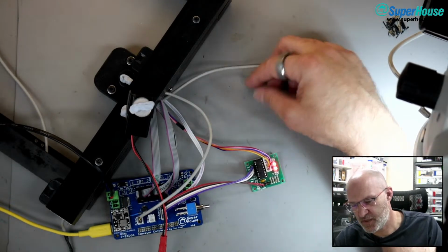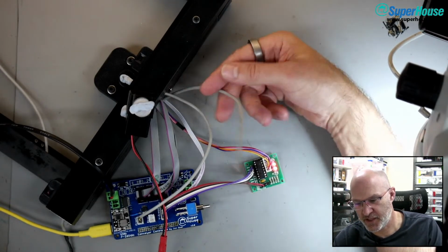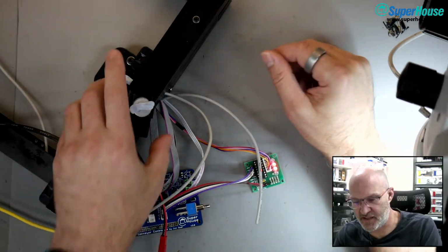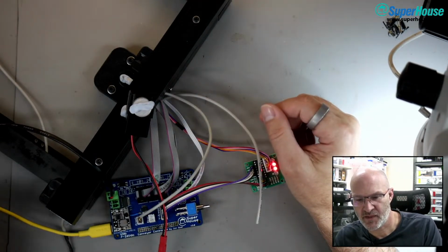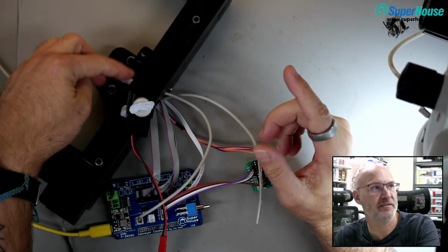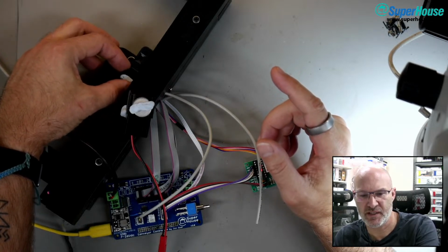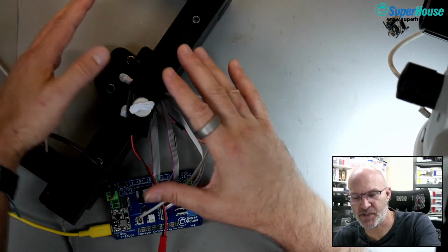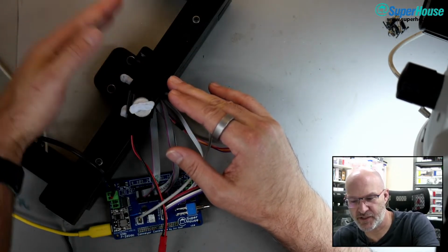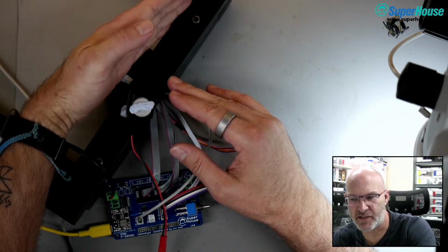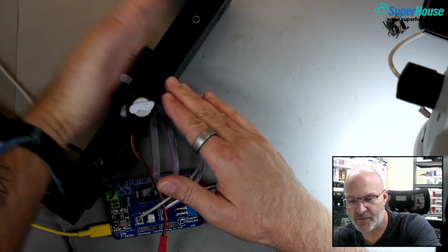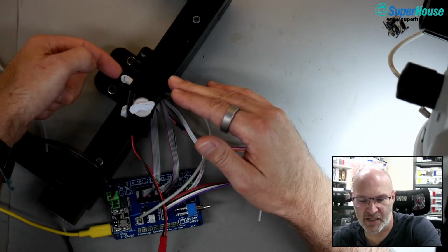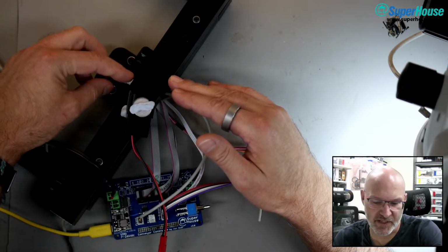Yeah, I don't know. To me, at this point, all of this feels a little bit like premature optimization. It's like trying to solve a problem that we haven't seen yet. I understand anticipating that this could be a problem, but this stepper is not super strong. So worst case, if it went out of control and lost its position and it was closing the conveyor, so moving the back rail towards the front, and it overshot and basically jammed into this, what would happen is the stepper would probably just start skipping on this little drive gear.